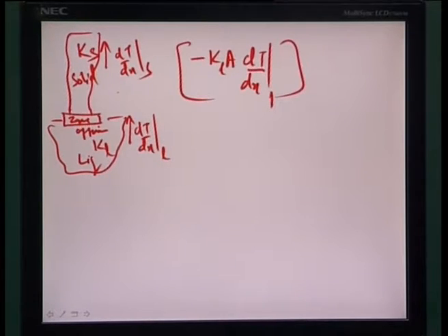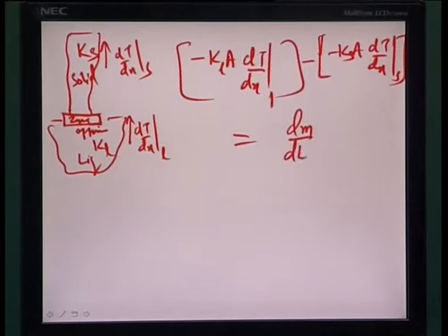The heat across the zone of fusion is minus Ks times A times dT by dx in the solid phase. And that essentially is the total amount of heat which passes into the solid phase from the liquid phase. And if we consider dm by dt as the formation of solid from liquid, and L be the latent heat of change of state, then this amount of heat needs to be lost from the liquid to achieve the solid.